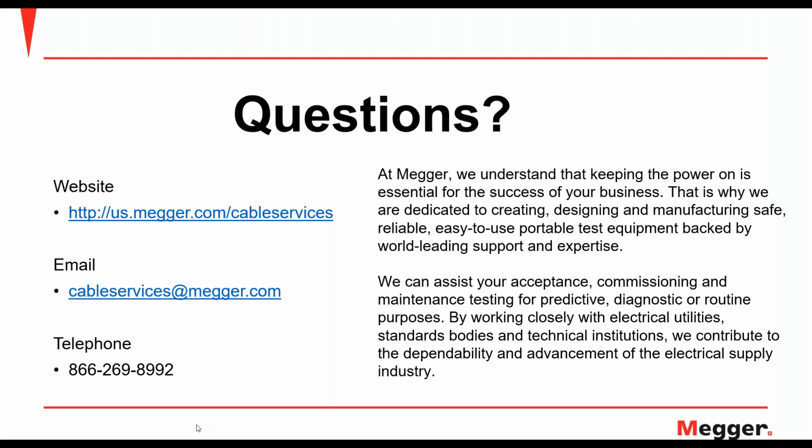Thank you, Michael, for the question. If we review the IEEE standard 400.2, it defines the test voltage, and says the voltage levels, based on worldwide practices, are from less than 2 U0 to 3 U0, where U0 is the rated RMS phase to ground voltage. The standard provides a table based on the most common voltage designs or manufacturers. When we have these tests, for this 6/10 kV cable, we need to follow that. If this is for installation acceptance, it could be up to 3 times U0. If this is for maintenance, it could be 75% of this.